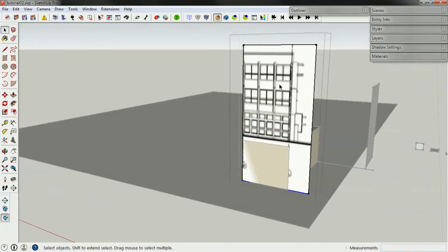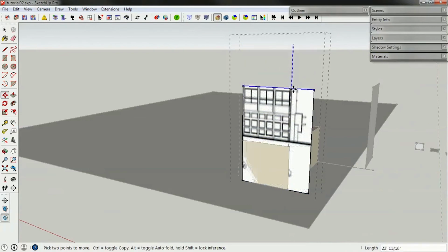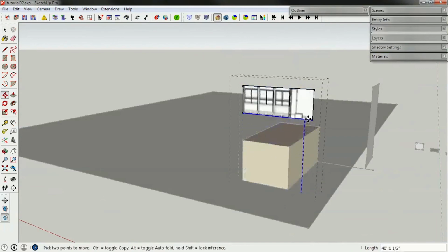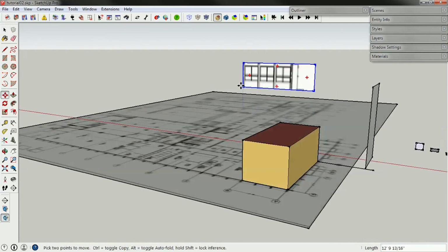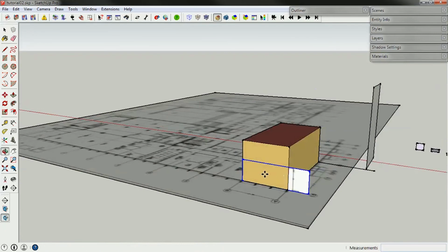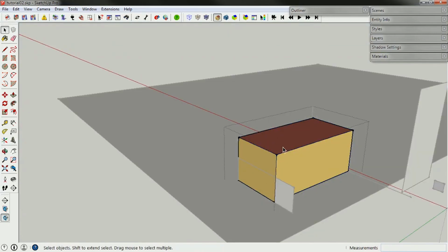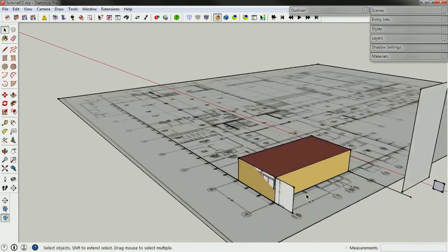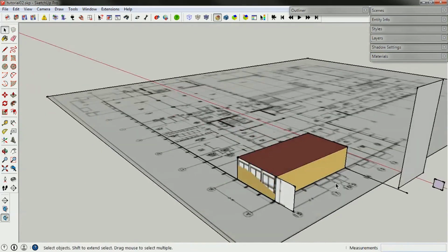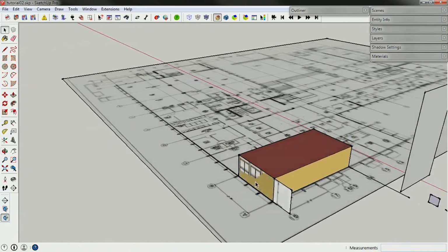And so I'm going to make sure this is close, and it is, and it looks like this is aligning nicely. So I'm going to assume that the top of the ceiling is somewhere around there, and the floor is somewhere around there, and that would be how tall? 13 feet. I think that's about right. I think it's probably about 14 feet, so we're close. And now I'm going to align this vertically like so. And I want to align my zone as well, so I'm going to double click into the zone, press P for push, and then align the roof to that edge. So what I've made now is the boundary of my air. Remember, this is really an air model, and so the volume of air is contained by this box.